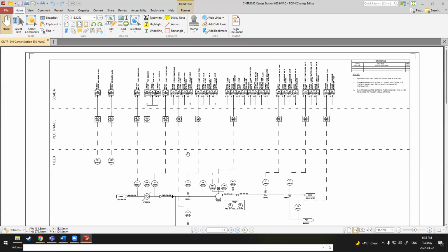So this is the order of designing any station that I've done in the last 16 years. We're normally given the devices that we want to install. We have to figure out what IO is required for that. Once you know your IO list, you can count up what you need and pick all the cards that you require. Once you have all the cards, pick your processor, build your rack. Then you would build your terminal, and that's where we're going to stop with this assignment.